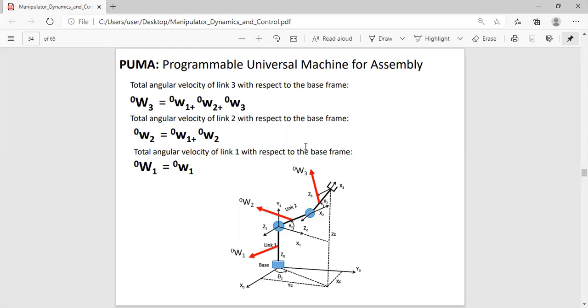But in general, every rigid body will have an angular velocity vector, and it could be arbitrary. So for every link, we're going to make it absolute. Here's the one on link 3, here's one on link 2. So simply adding omega 1 plus omega 2, this is the angular velocity vector on link 2. The angular velocity vector does actually have a reference frame. Okay, so these are our angular velocity vectors as rigid bodies.